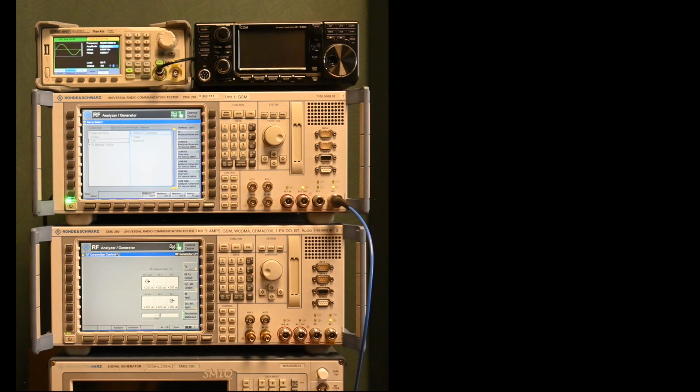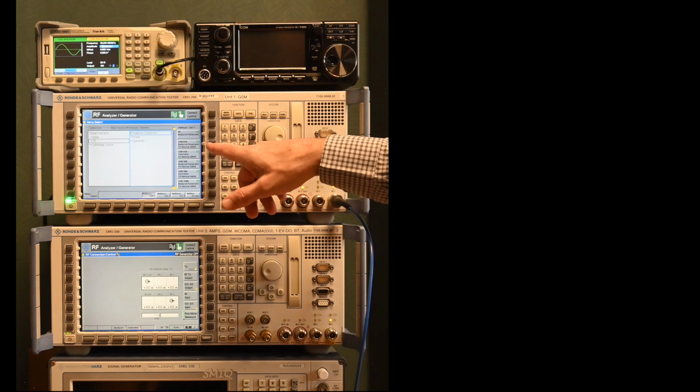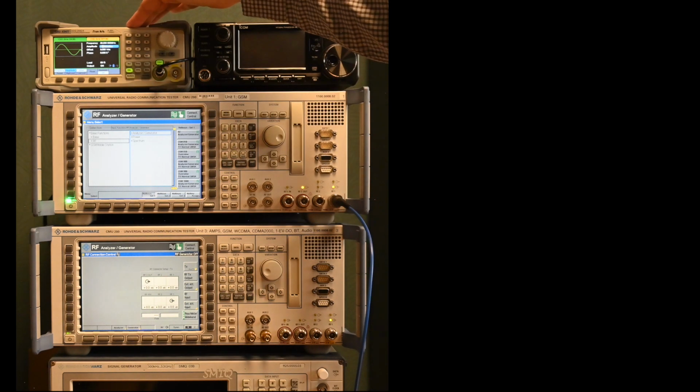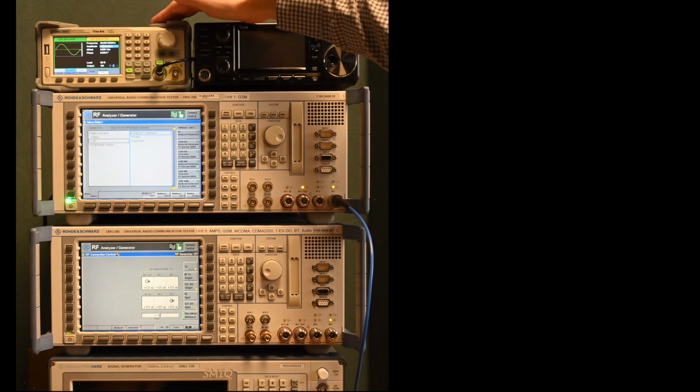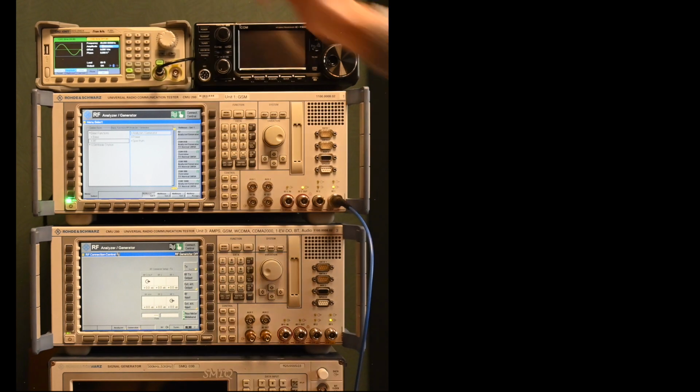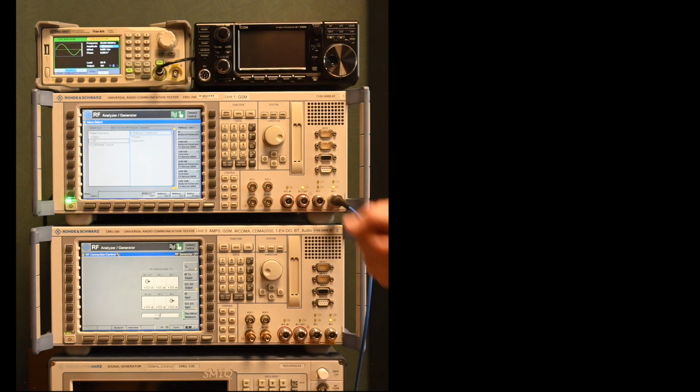In the next experiment, I'm going to measure the frequency specific power meter, and I'm going to use the unit over here. The incoming signals are coming from the Siglent signal generator, and I chose that one instead of the SMIQ that I used in earlier episodes, because this one can easily generate 2 different tones at the same time and combine them at the output. So I'm going to combine the tones of channel 1 and channel 2.